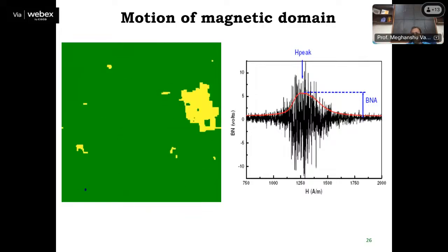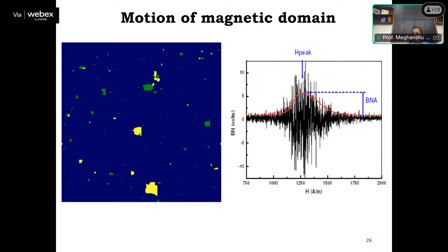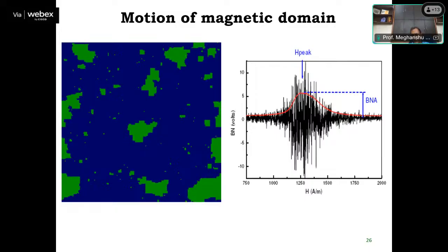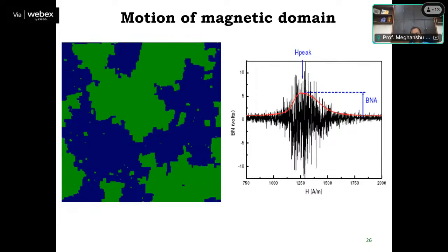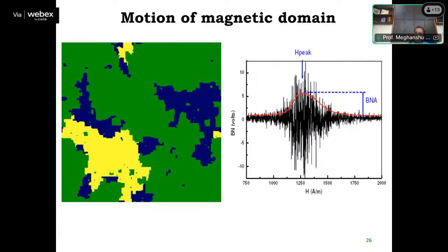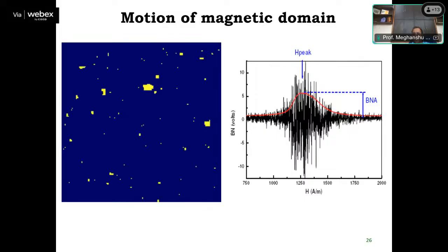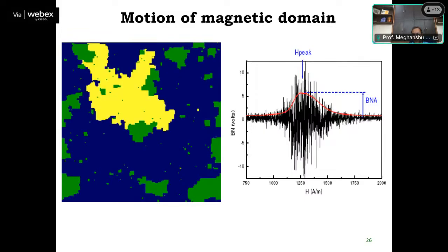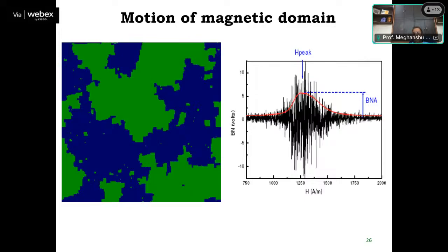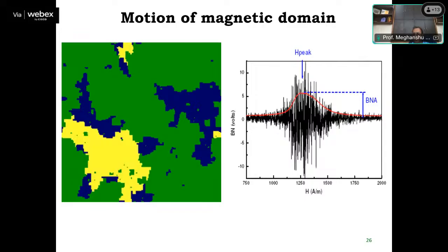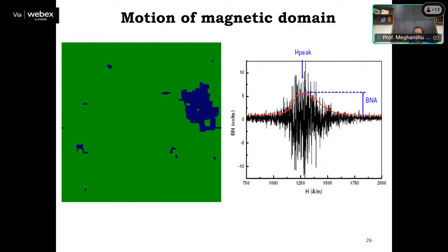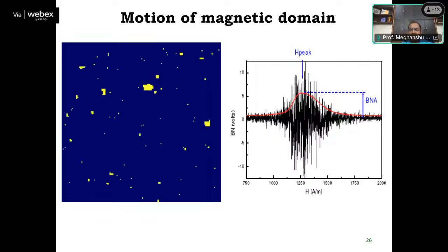This signal is very important to assess the health or to characterize the material. How can we assess? We can use mathematics, a mathematical curve, because mathematical curves have some parameters. You can see that a red color envelope or red color curve is there. That red curve has enveloped the Barkhausen noise signal or this raw signal. This curve is utilized to assess or to characterize the material.